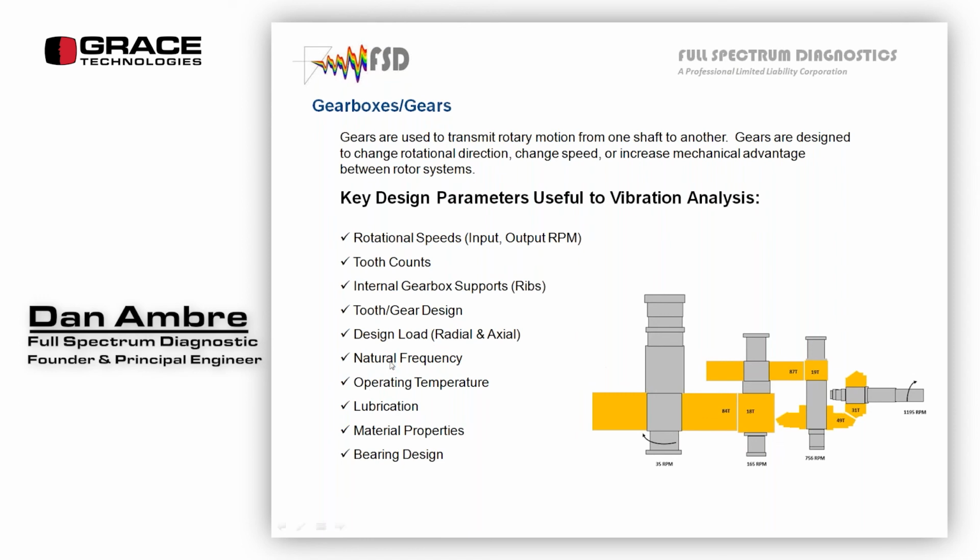Natural frequencies. Natural frequencies in gearboxes usually come from looseness, misalignment, backlash, things like that, any normal type fault that you'd see in any rotating system. But in this case, it might ring the gear. So a little looseness in the gear mesh, you get a little chatter, you're hitting one tooth face on the other, and you excite natural frequencies. It's like ringing a bell. They have an interesting signature in the spectrum, and we'll look at that as well.